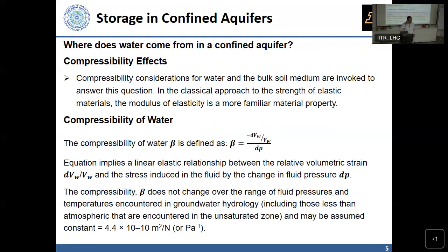So last class, somebody talked about subsidence, where that comes from. If this readjustment of the aquifer happens to be very large, then we will have soil subsidence. And as I said, there are theories for that. We have to make a few changes to our governing equations to account for subsidence and also allow for the fact that in this case, the soil particles are actually moving as well a little bit. But either way, the two important things are going to be compressibility of water. That's going to allow some water to be released.